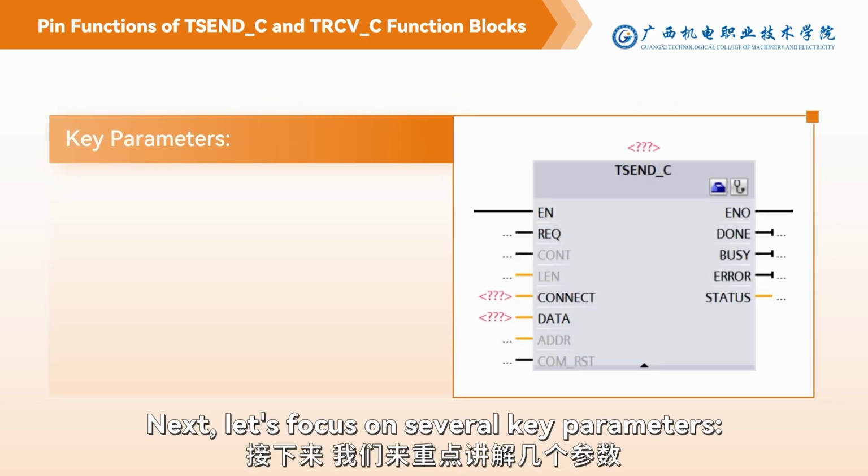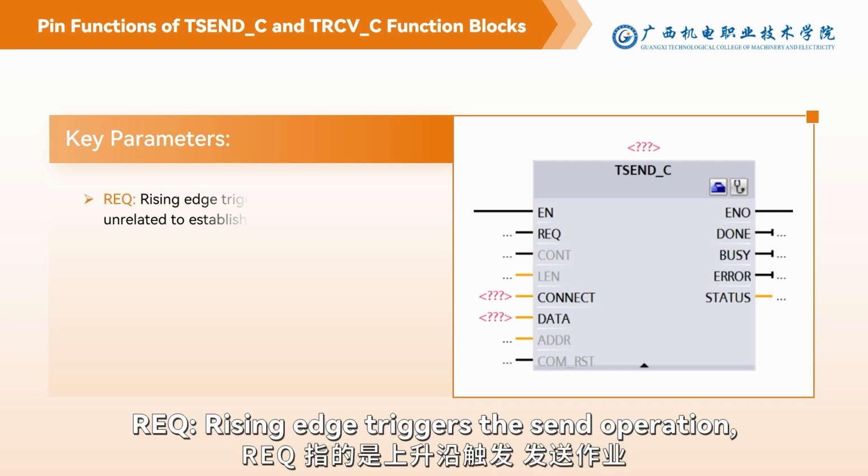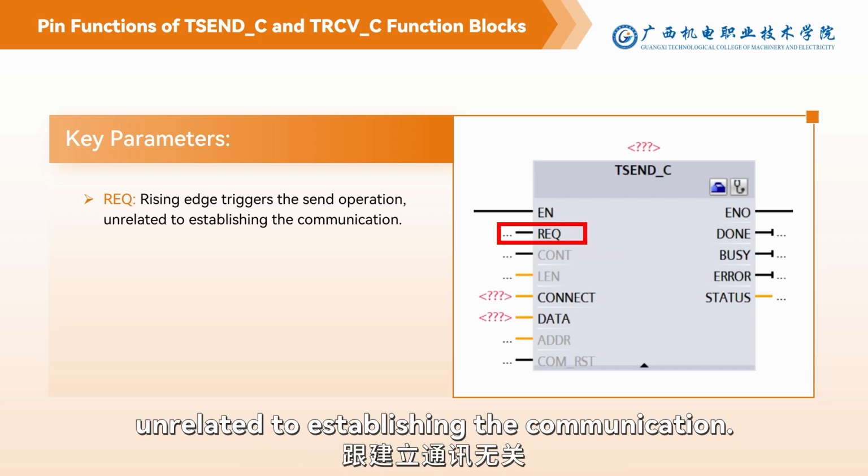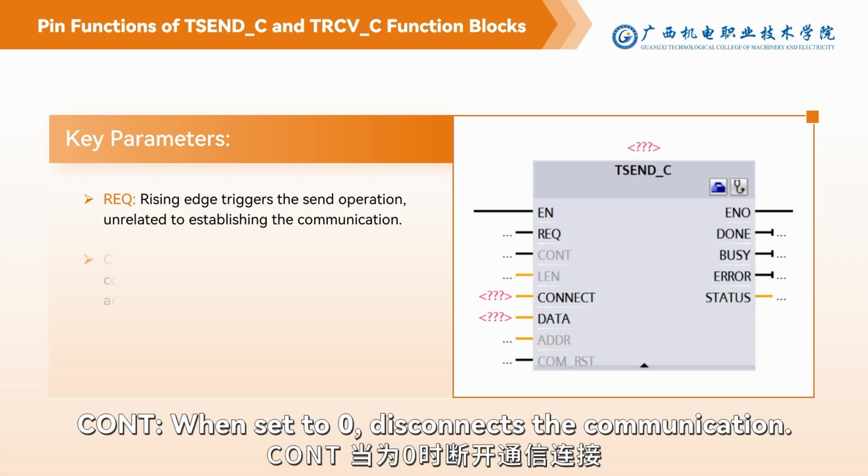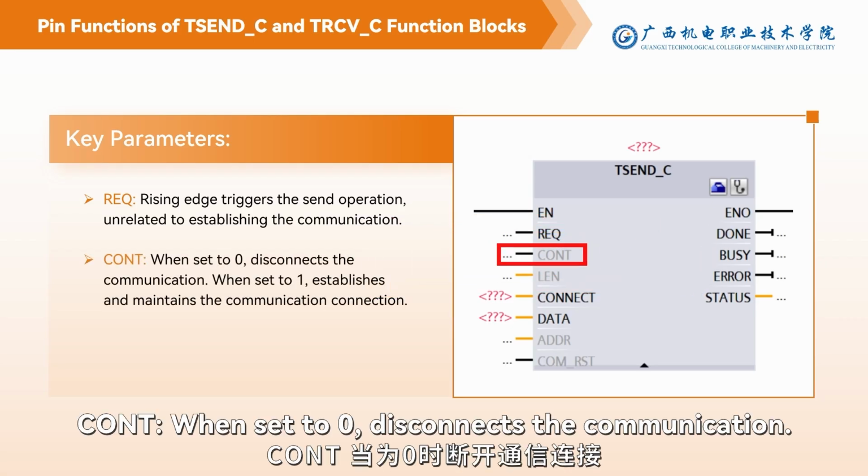Next, let's focus on several key parameters. REQ, rising edge, triggers the send operation and is related to establishing the communication. CONT, when set to 0, disconnects the communication.